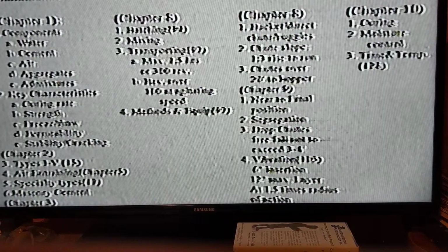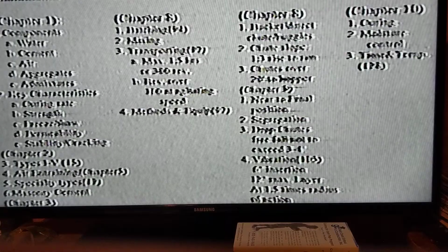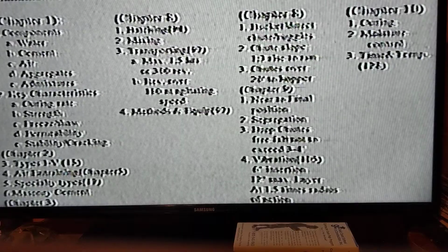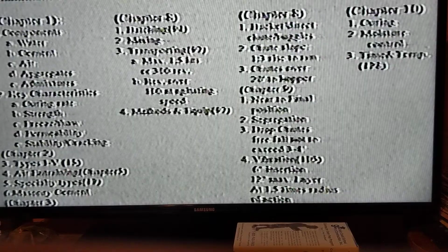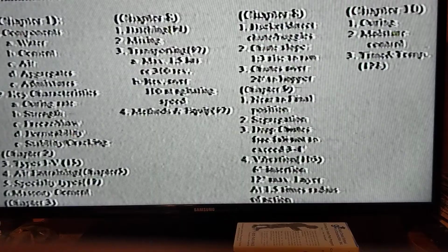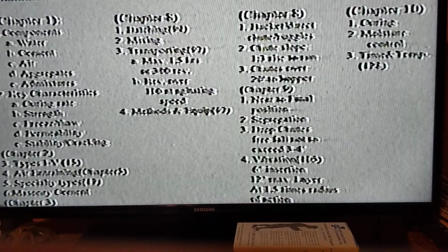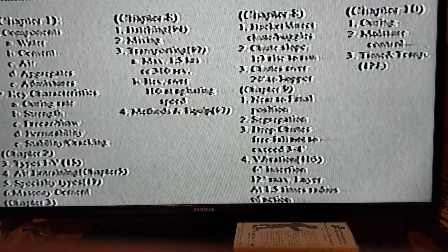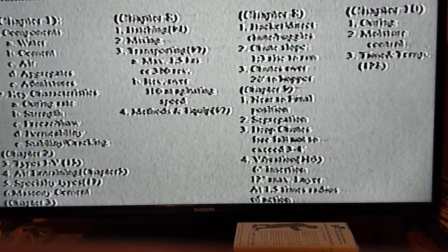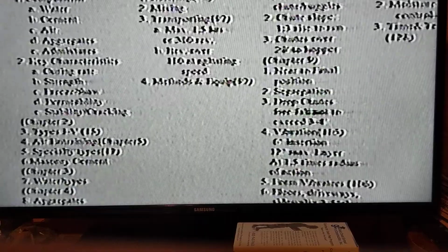Chapter 3 deals with types of water and their effect on concrete. As an aside, you may notice this: in the early 1900s, there was a period of time in South Florida where they ran out of sand. Well, what happened was they went down to the beach and they used beach sand. And now, on those houses where that was done, you can go around that house and with your finger, you can start scaling the house away and it won't stop. It'll just keep scaling because that type of water and sand, non-standard, created additional problems to the mix, and now those units are deteriorating. Chapter 4 deals with aggregates and the way in which aggregates are found and classified and measured.